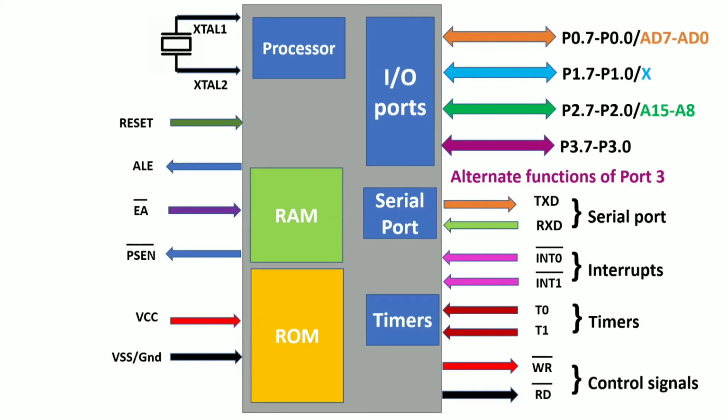If you take any simple device, that's why we make the multiplexed address bus and data bus combined with port 0, so that we can reduce the size of your microcontroller. If you have 2 different sets of pins for port 0 and for the address bus and data bus, we increase the complexity. That's why the Intel engineers, intelligent people like you, thought: why can't we use the multiplexing concept to make the address bus and data bus multiplex with port 0?